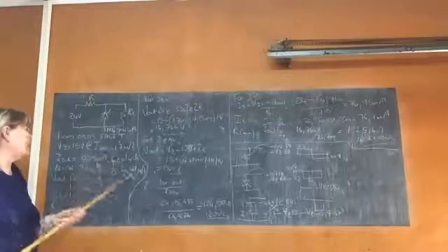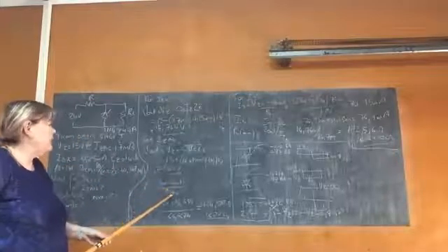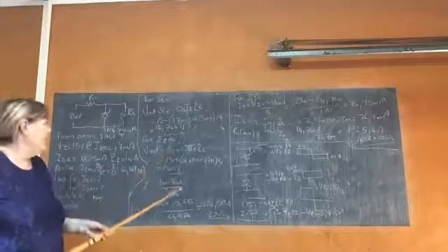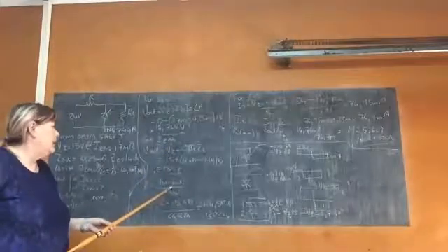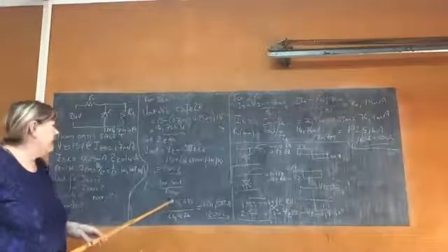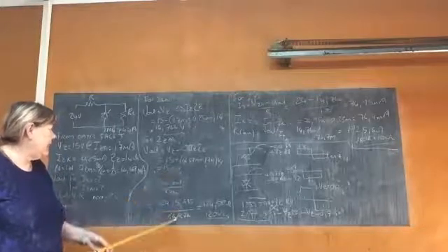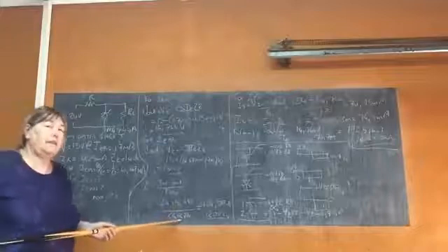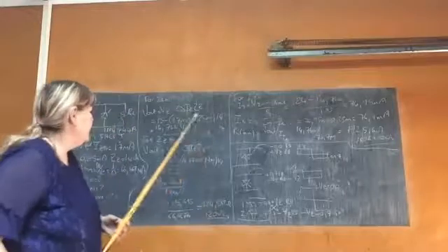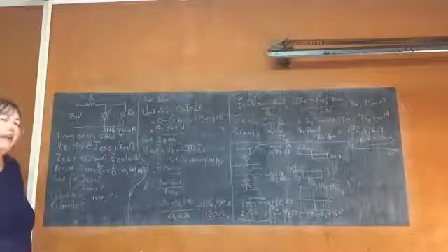Now I must calculate R, the R value. I say V in minus V out over IZ maximum. And in the example in the book, there's a mistake. So if you don't check the Zoom session, you will not pick up the mistake. So it's your 24 minus your 15.65 over your 66.667 milliamps, and you get 124.569. But they ask here, what is the nearest available value?